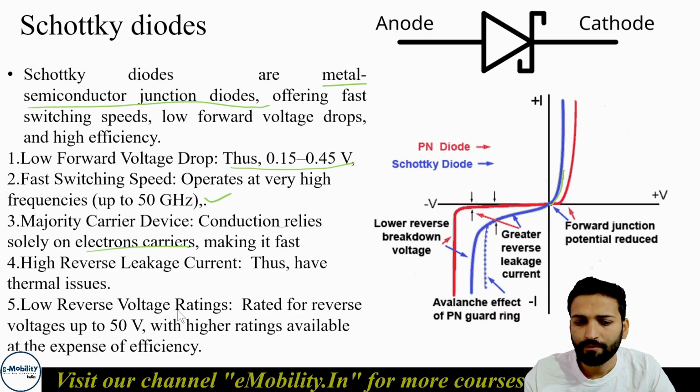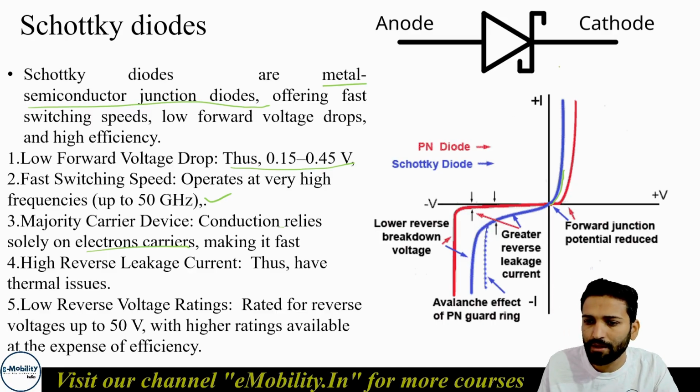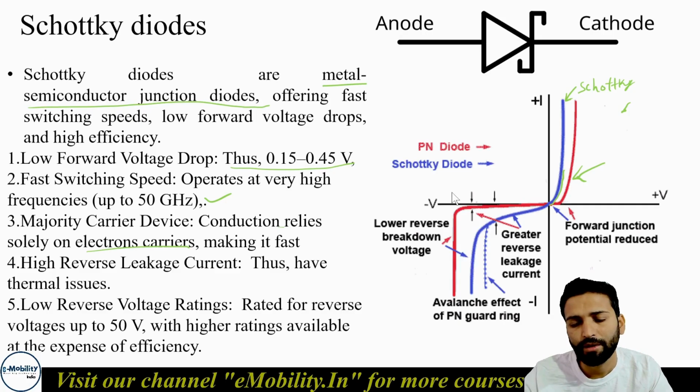There's a reverse voltage also. So this plot shows a difference between a normal PN junction diode and a Schottky diode. You can see that a PN junction diode has a higher cut-in voltage, and this blue one is showing a Schottky. The Schottky will have a very low reverse breakdown voltage, while the PN junction has a wider junction, and that is why it will have a very large breakdown voltage.